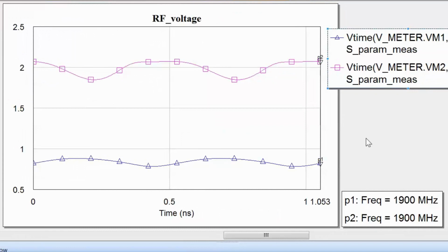So the pink curve represents the voltage at our collector terminal. And you can see how this voltage exhibits a considerable level of fluctuation, and that is because it's got an RF ripple of the frequency which we're operating at superimposed upon its DC level. And this can create a lot of trouble, because of course the bias of the transistor is then not stable, and all these fluctuations in the bias may create some oscillations with the transistor, may make it unstable and hence not operate efficiently. So there's all manner of trouble that can be stirred by this sort of thing.